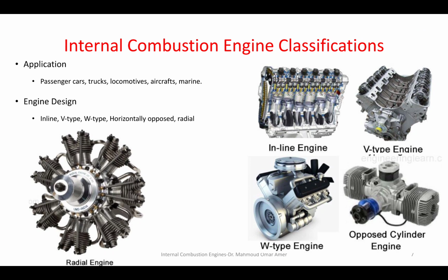If we put the cylinders beside each other, they invented the V-type. We have two pistons moving with an angle of approximately 60 degrees, making a V shape. Okay? So if we have a V8, it will be the same length as an inline 4, but it will be slightly wider.